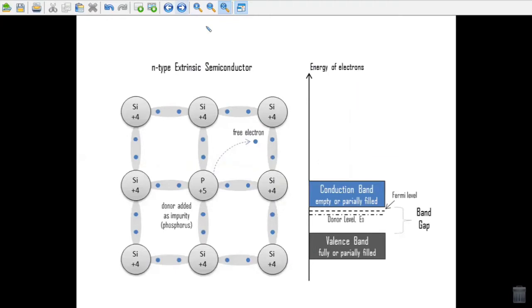A real semiconducting crystal grown in a laboratory, no matter how pure, always contains some impurity atoms in addition to other imperfections, which create their own energy levels termed as impurity levels. These levels may occupy positions anywhere in the allowed and forbidden bands of the semiconductors.